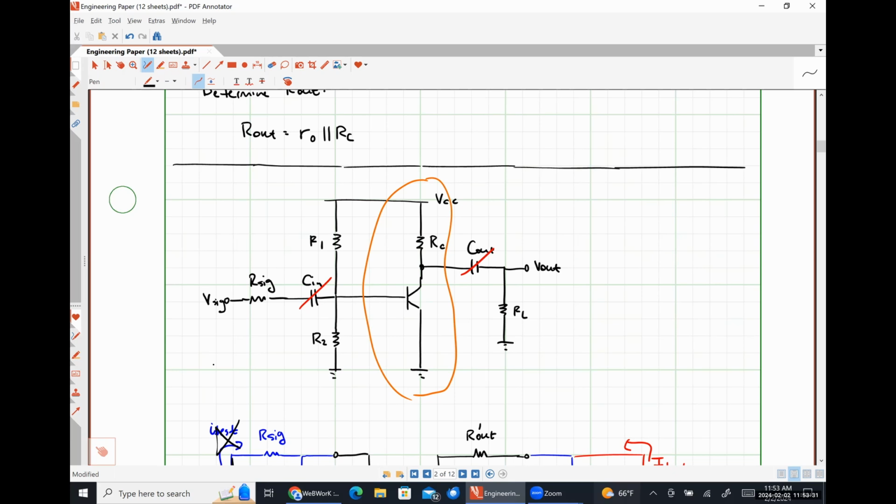We also know how to bias a network like this because we've been doing it, right? So effectively, if we know what our voltage gain is, and we know how large our input signal can be, then we know the size of the signal that's going to be superimposed on the top of the DC operating point of the output voltage. So we effectively just want to make sure that the DC operating point of the output voltage is low enough so that the highest part of our AC signal doesn't exceed VCC. And we want to make sure that the DC operating point of our output voltage is high enough to where the low parts don't hit saturation. That's it. So we just want a bias point somewhere in the middle, which will establish our transconductance and all of that kind of good stuff.